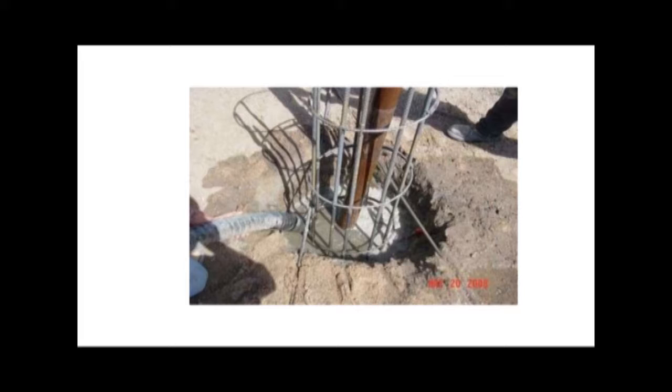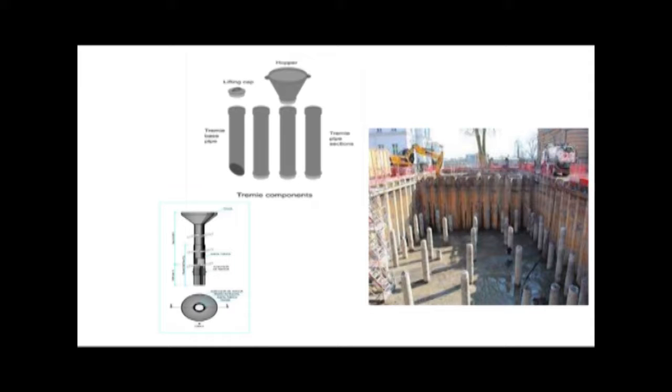Also, there is the loss of mix as we go for the concreting in the direct mud circulation method. Because we put water or bentonite slurry into the pile cavity for the excavation of the earth, there is water already present in that cavity, and when you pour the mix of M20 or whatever into the cavity, the concentration of the mix gets decreased.